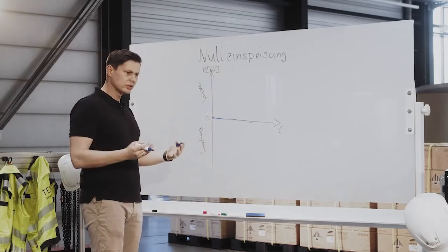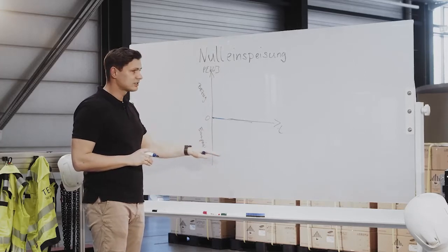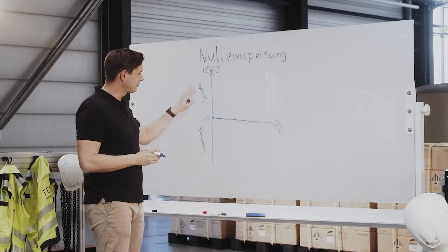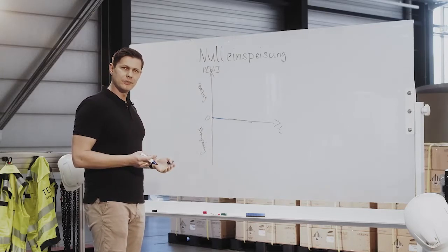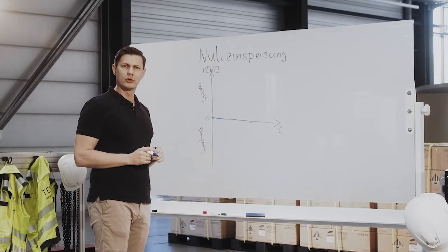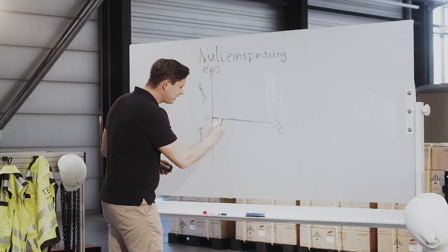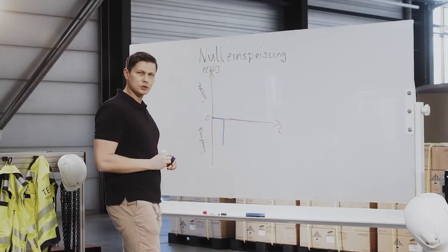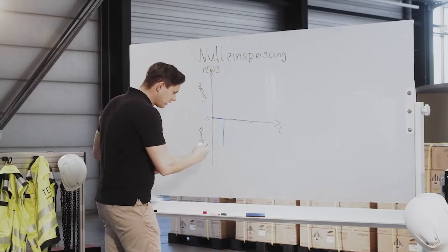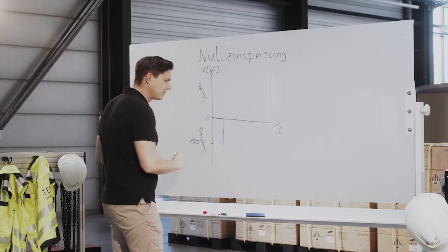In the following, I can say that we now assume load shedding for larger consumers. We have existing generation via a photovoltaic installation, and a larger consumer, such as a machine, is switched off in the following example. At this moment, I am producing a feed-in peak. I would assume that it is 100 kilowatts for the purpose of this example.